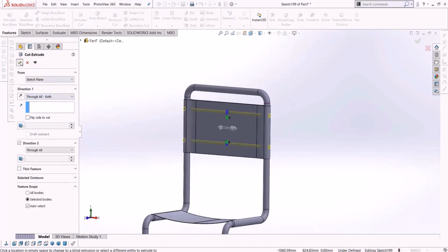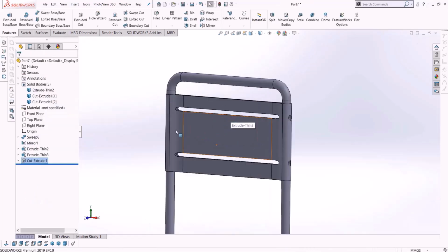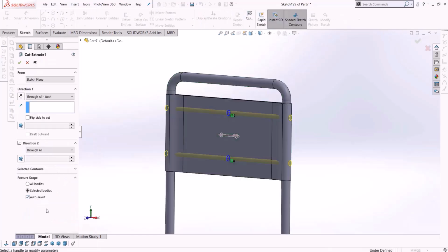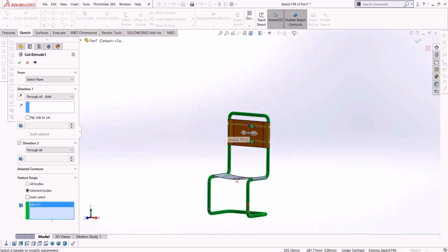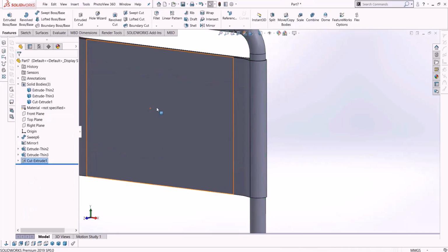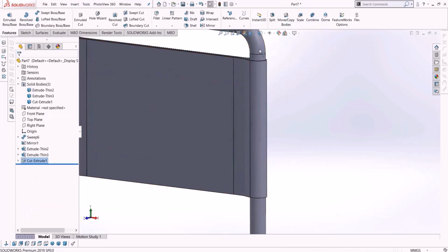Now notice that in the default state, the selected body is highlighted, or in the all body state, it selects the entire object for me. Well, that's not what I want. I want to edit it in body mode. So I will say, please only affect this object, this body of ours, because removing the merge creates another body. It doesn't interfere with our work, so these holes are created now just for our rod.